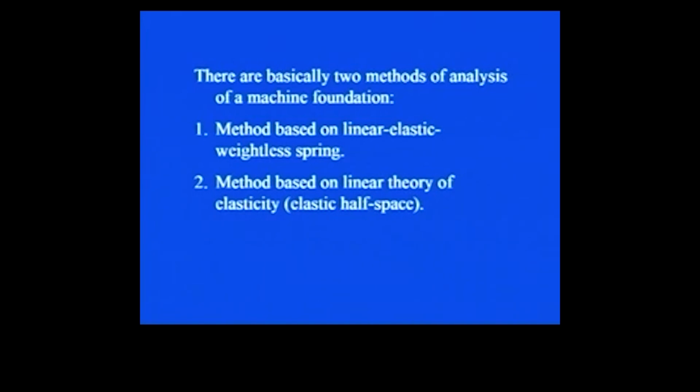Basically, there are two methods for the analysis of this machine foundation. First is the method based on linear elastic weightless spring, where, as you have already seen, you can represent the system by a spring and mass system. Then the method based on linear theory of elasticity, that is elastic half space. So first let us see how the method based on linear elastic weightless spring works.